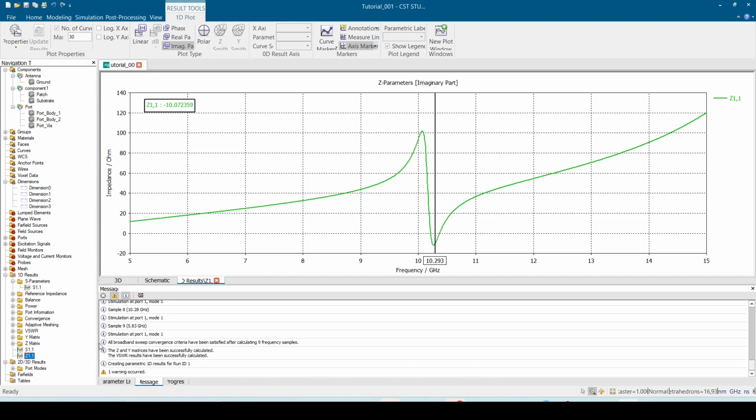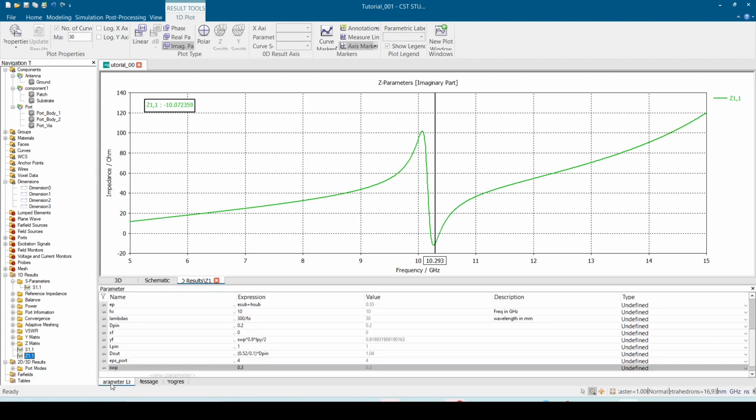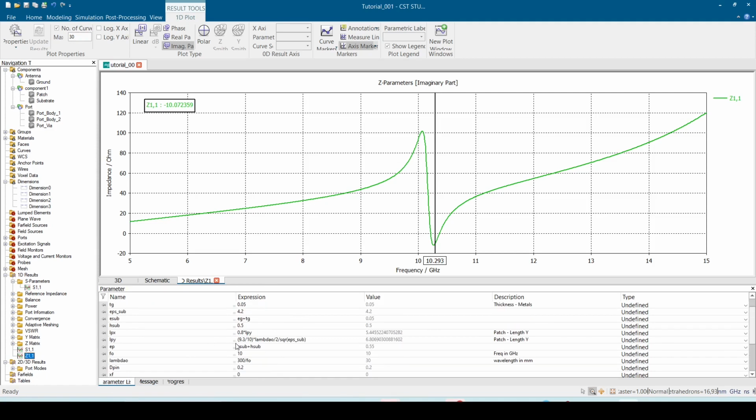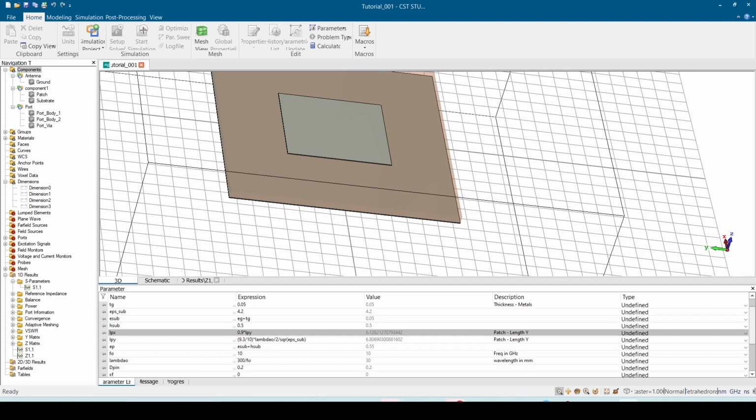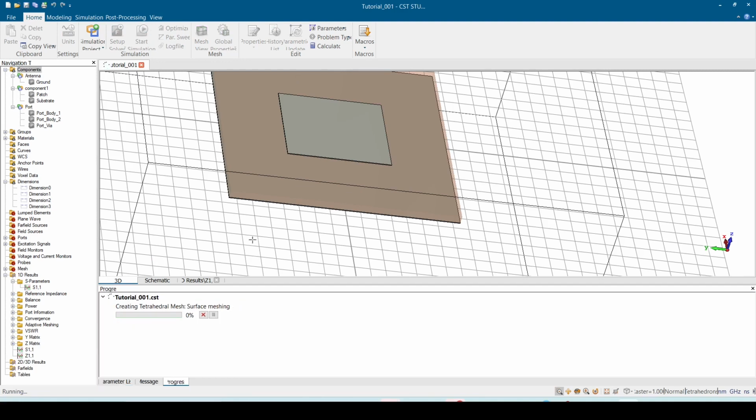And here comes the role of the width of the antenna. So for example, here we can see that the antenna is more inductive, right? Because most of it is in the positive values. So if we just decrease the patch, or if we increase the width of the patch, we can actually improve the matching a little bit more. So if I say, for example, get 0.9, and then let's see what we'll get here, 7, and then press start, and just let's do a quick comparison, and then this will be the last thing.